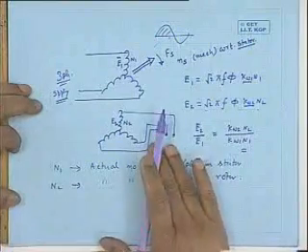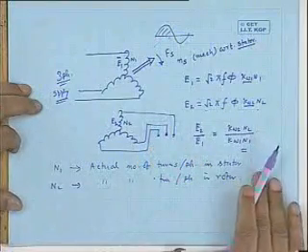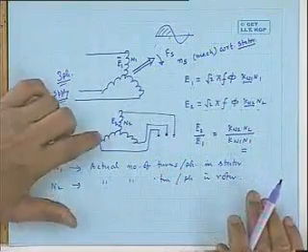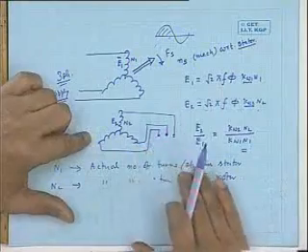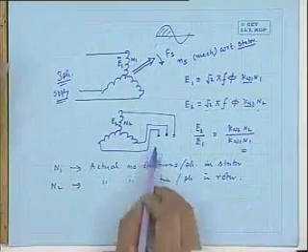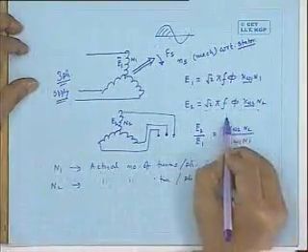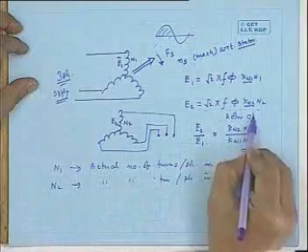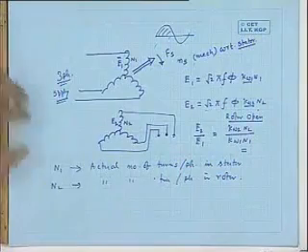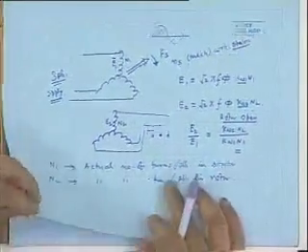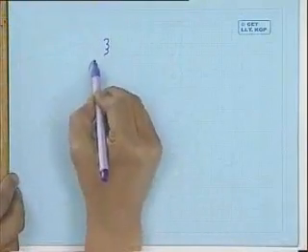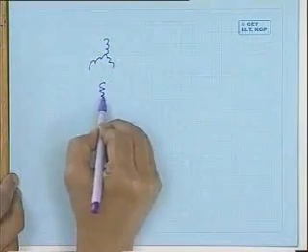So perhaps one may think it is a kind of transformer where you can supply a load from these rotor terminals. In fact, there are transformers called induction regulators, where the rotor is not allowed to rotate and it is supplied from the voltage that is there. So this is when the rotor terminals are open, rotor open. Okay, today I have enough time just to tell this much.